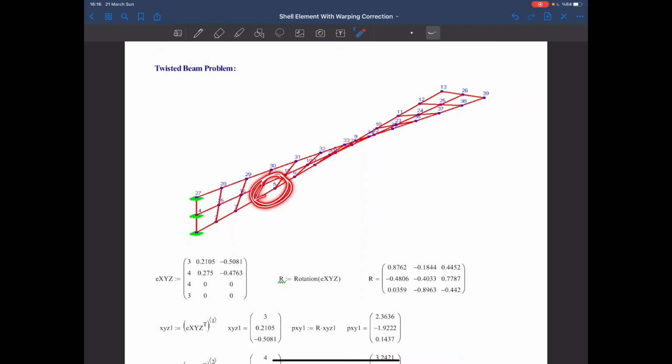So here the first thing that I'm going to do is to show what we were doing for this, just for the fifth element. This is 0, 1, 2, 3, and 4. So these are the x, y, z coordinates of that element. Now we calculate the rotation matrix. The rotation matrix is calculated again. Let me draw in this way. So the unit vector should be something like that.